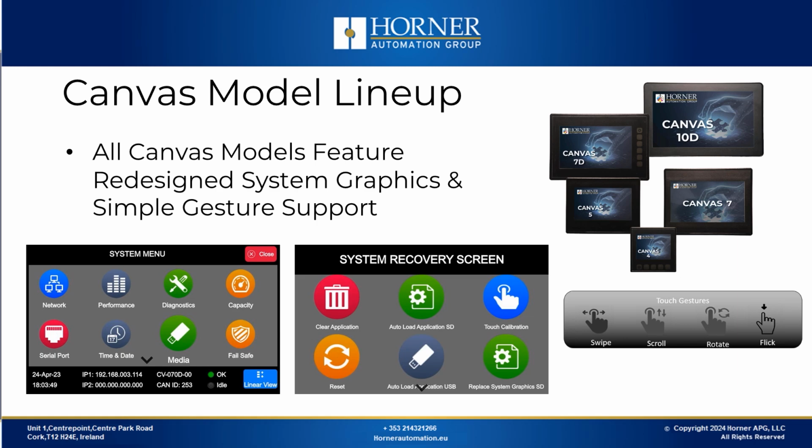Canvas is the first Horner OCS product line that supports gestures. Canvas is still primarily a resistive touchscreen-based hardware platform, not capacitive touchscreen-based. This is because a resistive touchscreen is a much more reliable option for industrial applications and is the best option if you have a glove-based operator. So Canvas supports simple gestures such as swipes, scrolls, rotates, and flicks.